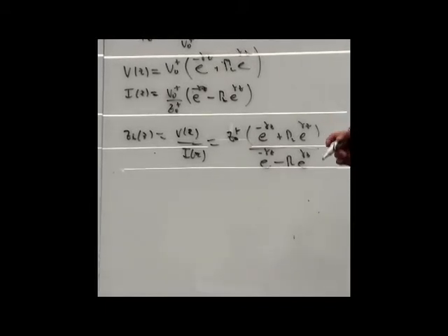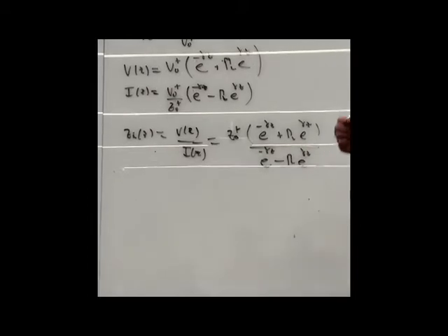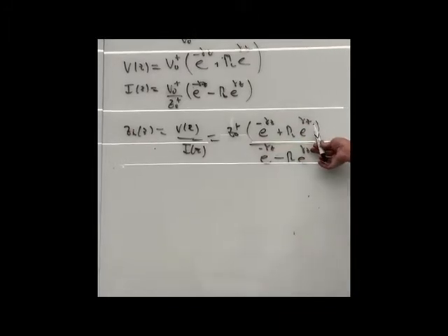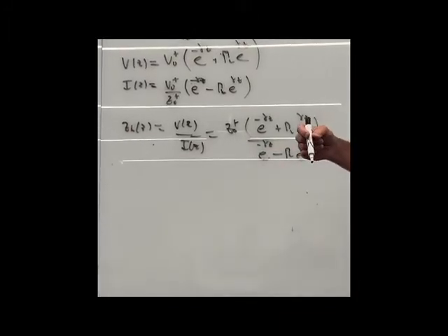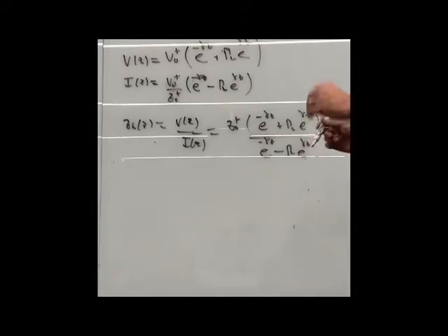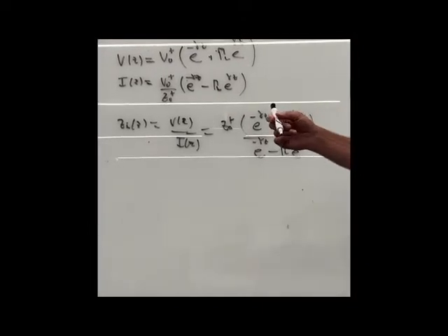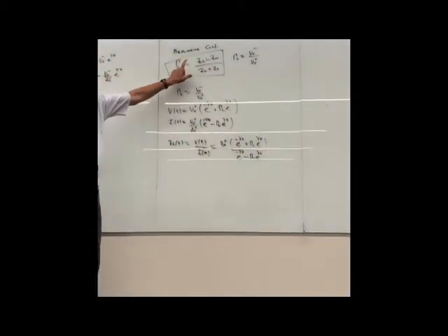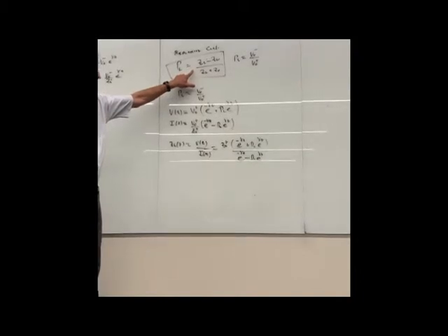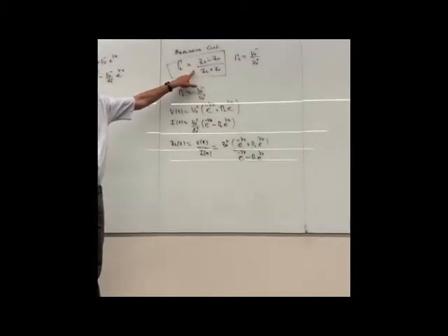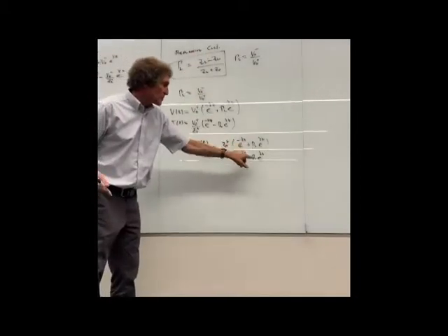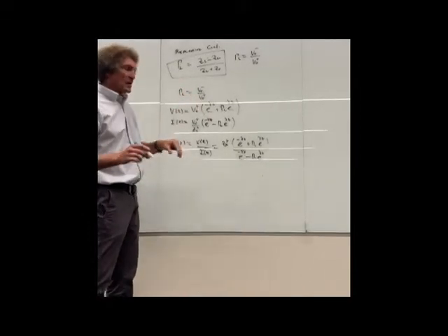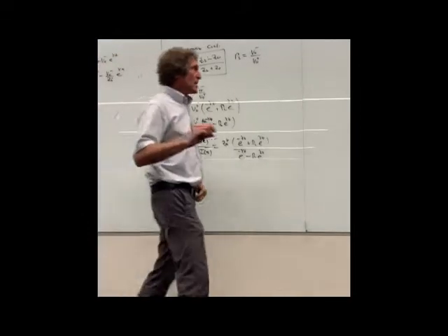You know what the problem is? I have 1, 2, 3, 4 terms that are exponential I have to calculate. Really, I only have to calculate this once and store it, but I have to use it twice. And I need the reflection coefficient. So what we can do, and I'm just going to tell you this, I don't need to do it now, is replace that reflection coefficient with this right here, and simplify. This is an exercise in the book. So I would stick it where those reflection coefficients are, and then multiply top and bottom by ZL plus Z naught. And this is what comes out.